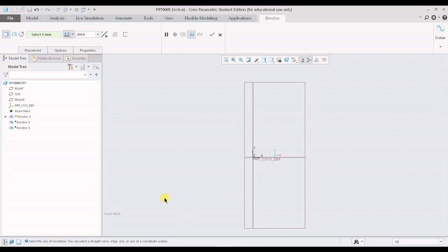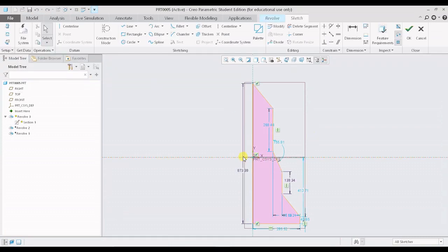So now I have to select the vertical axis, which I decided it to be the y-axis. But if I'm selecting the x-axis, I will not be getting any revolve option, because you can observe over here, if I'm selecting the x-axis, the software will not understand, or it will not try to interpret the geometry, because the geometry has to be above the particular horizontal axis if we are wanting the axis of revolution to be the horizontal axis.